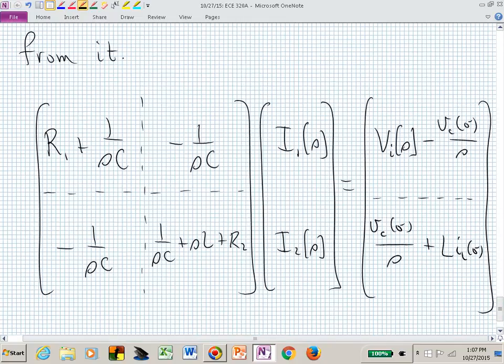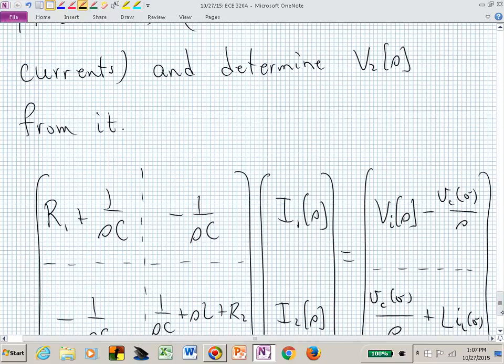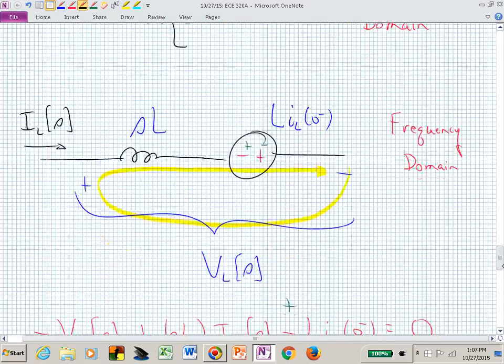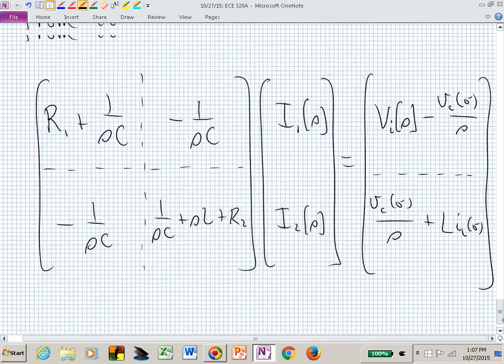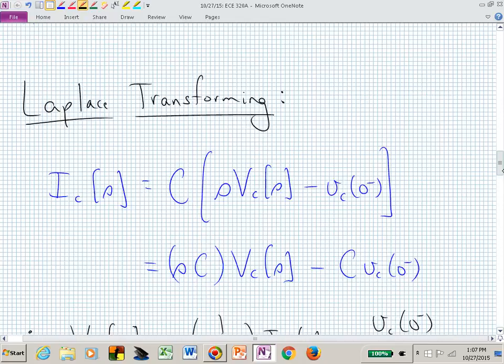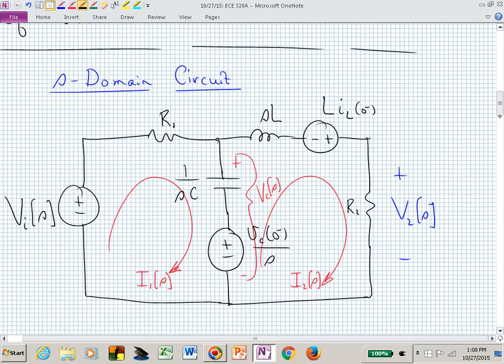Because we usually have USC, USC is negative. Minus 1 over SC, where did that come from? In either term, right? So if we look at the top row, if we were simply writing the first mesh equation in clockwise, this only works if you put all of your mesh currents in the same direction. They're all going clockwise to do it by inspection.